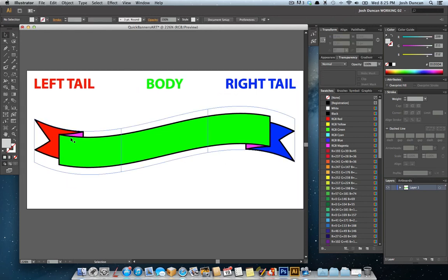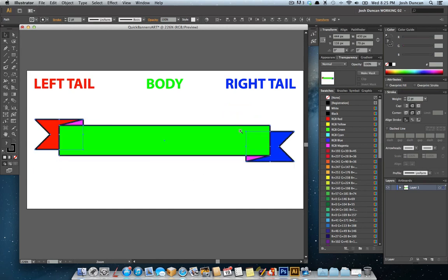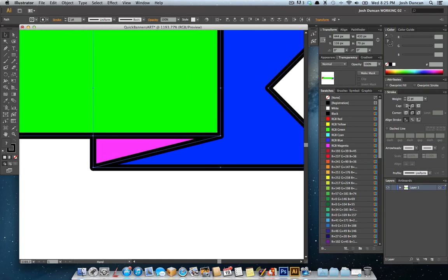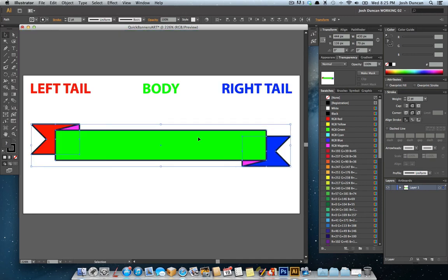Now, obviously, the colors are a little funky, but that's just for demonstration. If we were to go back and take off the rounded corners here, you'll see why you need to round them. You end up with these kind of funny ends. The angle here is so steep that you have to go in and play with the limit to try to get that to line up. Easiest way, just round the corners. As long as you're using small numbers, you really can't tell it from a distance.